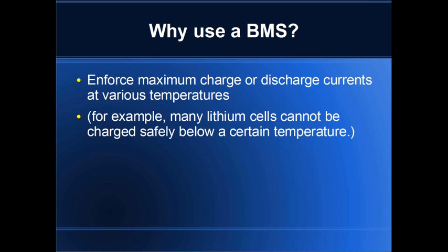There's other limitations. Some cells allow for pulsing. You can pulse at higher charge and discharge rates for very brief amounts of time. So there's other things that a battery management system can enforce.